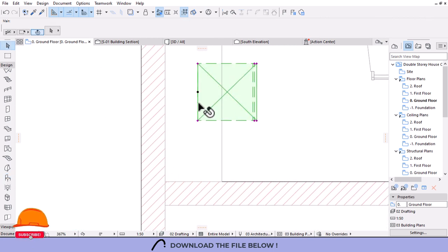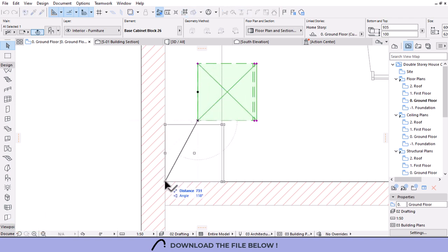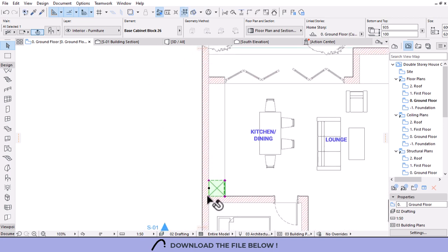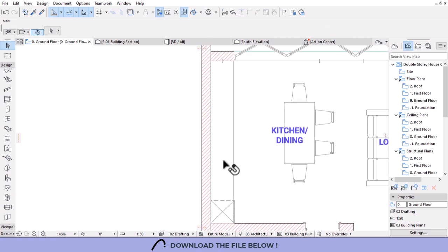When you select it, this black point, or the hotspot, indicates the back side of the cabinet. So I'll just pick or drag to the point here, and then I'm going to run multiple copies to there. But for you to know how many, I'm going to fit around 7 cabinets, but we need to measure. I'll press M on the keyboard and then measure this.